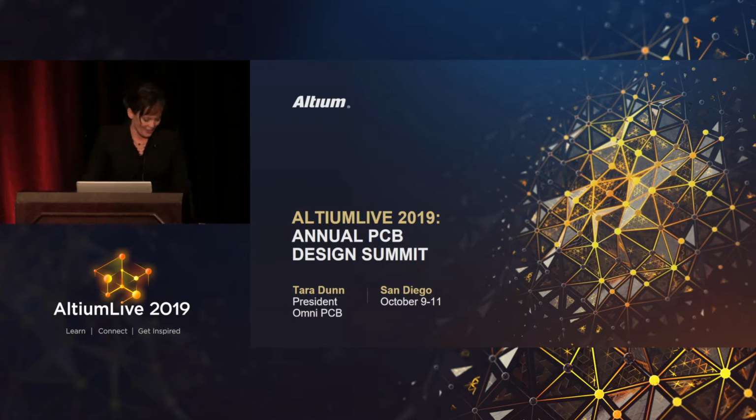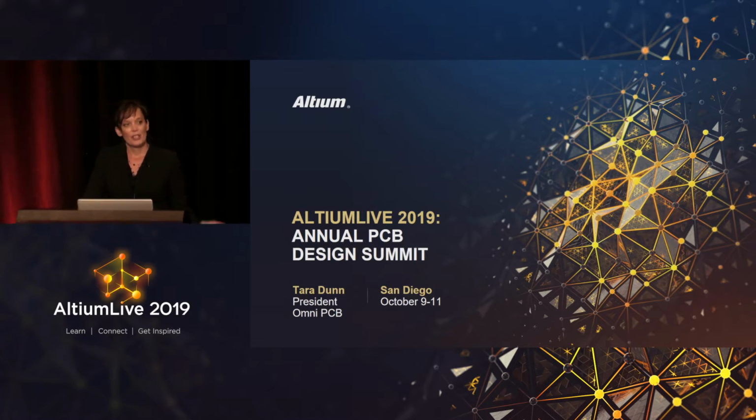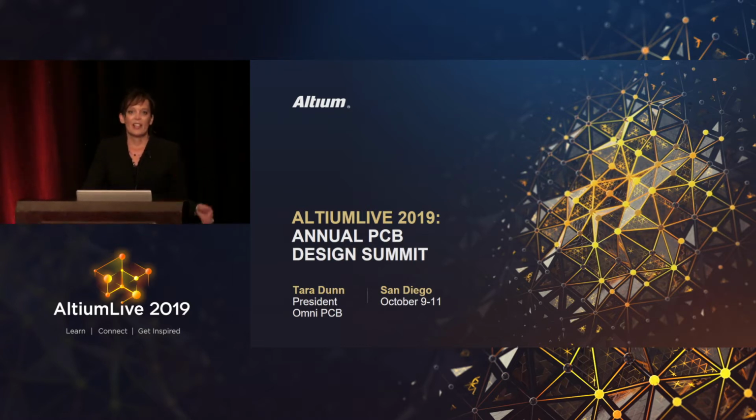The first one I'm going to start out with is one from about 20 years ago. It's the first one in my memory that was truly challenging. Like I said, it sticks in my memory still 20 years later. So the design comes in. It's a very simple double-sided flex. The trace is on the top side, solid copper shield on the back side, rectangular in shape. It's like 10 or 12 mil trace and space, very large, 12 mil drilled. Nothing out of the ordinary about that design at all.